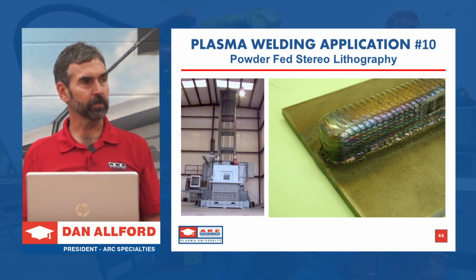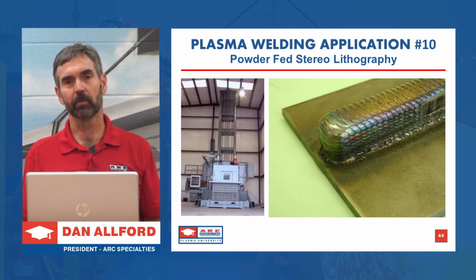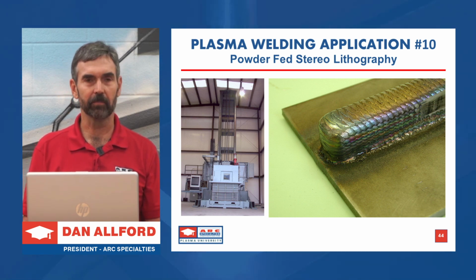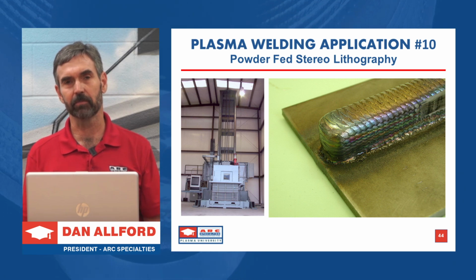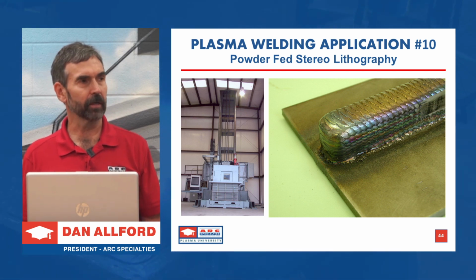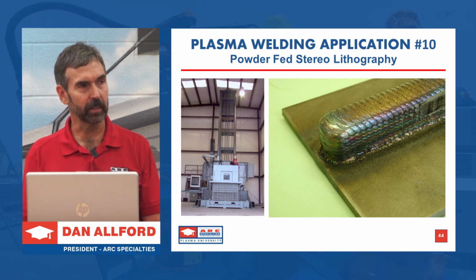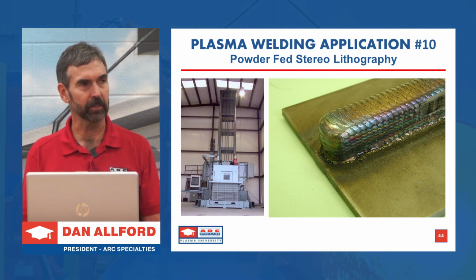Another good thing about plasma is you can see we have multiple hoppers. So as we were moving about this part, we'd actually change the chemistry on the fly with the multiple hoppers, and we could feed them through the same torch, which would be difficult to do with a wire feed system. Over on the right, you see a weld sample. This was titanium. We're getting over 150 KSI tensile strength.